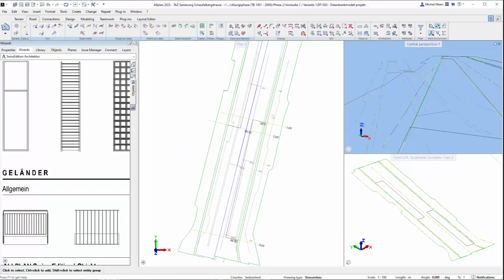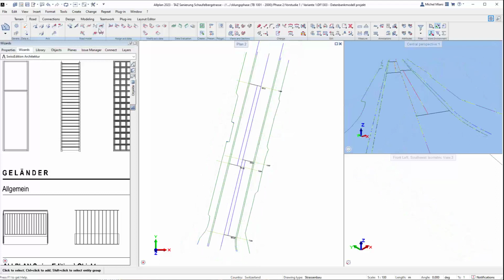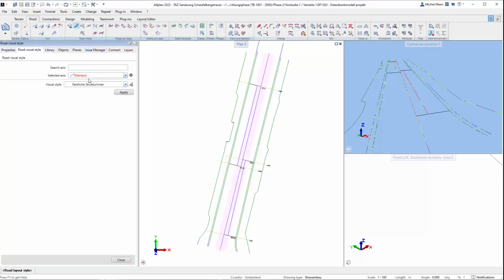When creating the limits, I set the street view to 3D polyline, so I avoid a long calculation of the database and the creation of 3D objects. After the limits are finished, I set the street view to 3D view. This way I can better view the result.